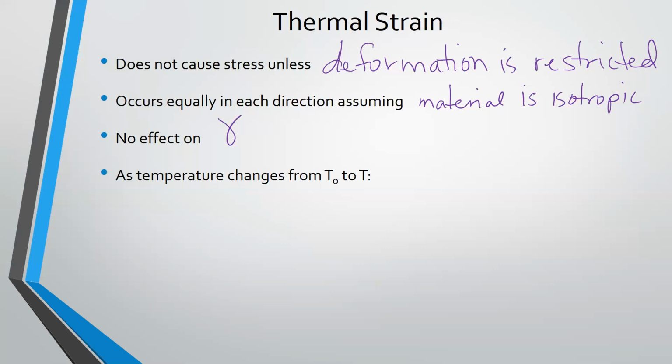We'll come back to this topic when we cover axial forces. We'll have some problems with temperature. But in general, if it can expand freely, there won't be stresses. If you've got constraints, there will be some stresses involved. Depending on the types of constraints, if it's constrained at both ends, we're going to have stresses throughout. If it's just one end, we might have localized stresses, but overall the body is fairly without stress.